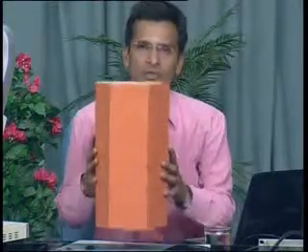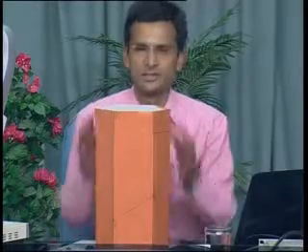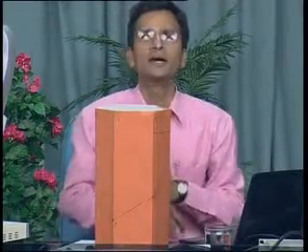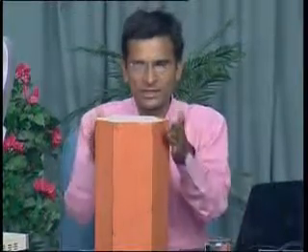This is a hexagonal prism. In the previous problem, we assumed that this hexagonal prism is lying on its hexagonal base. So we drew its top view like this, and the front view as a rectangle. But here something different is given. Here it is given that it is lying on its rectangular face. So this is a rectangular face.